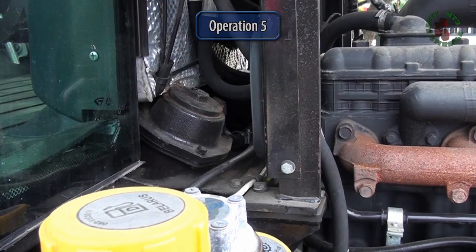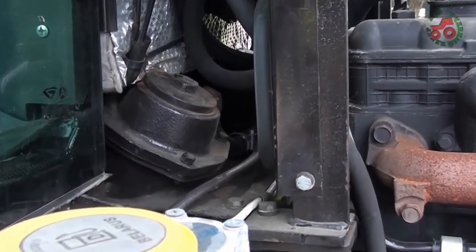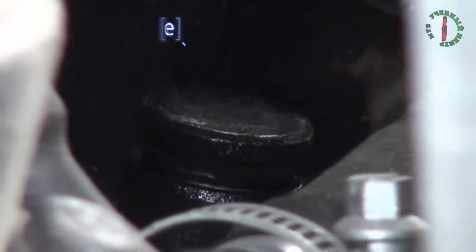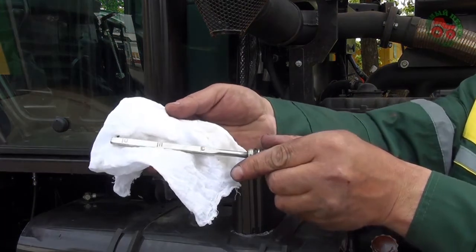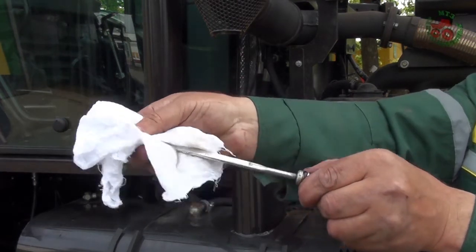Operation 5. Check oil level in the rear hitch oil tank. Check oil level according to the oil level gauge. Level shall be between marks O and P. If necessary, remove the cap of the filling neck and add oil up to the mark P.